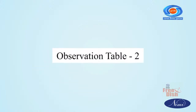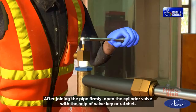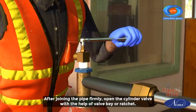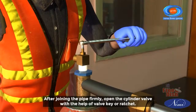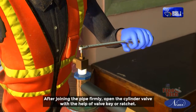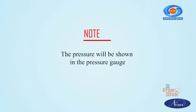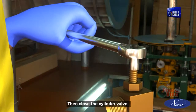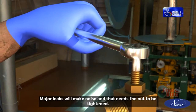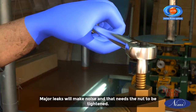Observation Table 2. After joining the pipe firmly, open the cylinder valve with the help of a valve key or ratchet. Note: the pressure will be shown in the pressure gauge. Then close the cylinder valve. Major leaks will make noise, and that needs the nut to be tightened.